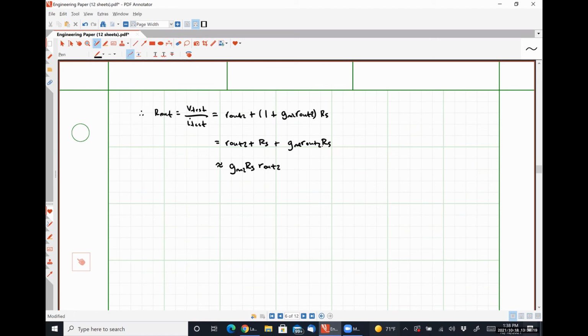So we effectively just have a simple scaled version where ostensibly, if we make that source resistor larger and larger and larger, our output impedance, the impedance of our current source, also gets larger and larger and larger, right? So on a small signal level, this is pretty legit.